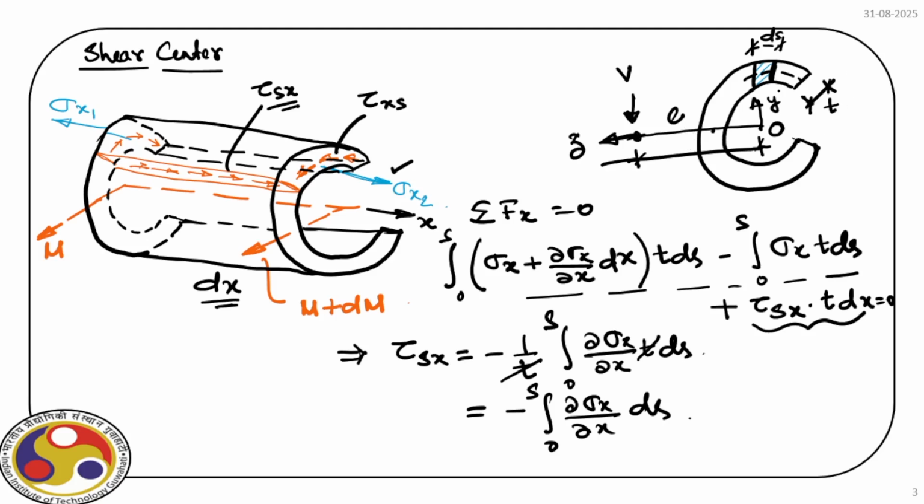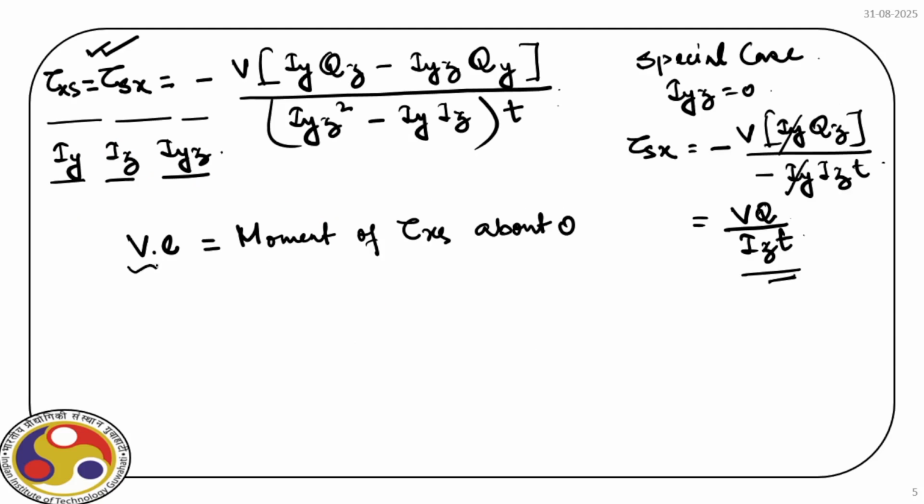So for this third path, we have already quantified the force Fx, and from the center of this force we know the distance. That distance will give us how much moment is caused by the force over this cross section, and if we integrate over the entire length of the path, we'll get the moment, which will be balanced by the moment V times e.